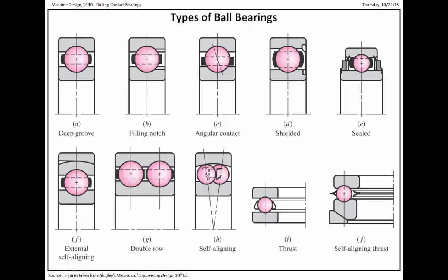All right, there's lots of different types of bearings. The ones that I think are important to us: the deep groove, angular contact, and we might say self-aligning. We'll see. We'll hand out some in class or look around at them to look more closely. Both the angular contact and the deep groove can handle some amount of axial loading as well as radial loading, radial loading being the primary thing that we care about. On the angular contact, they can handle more.